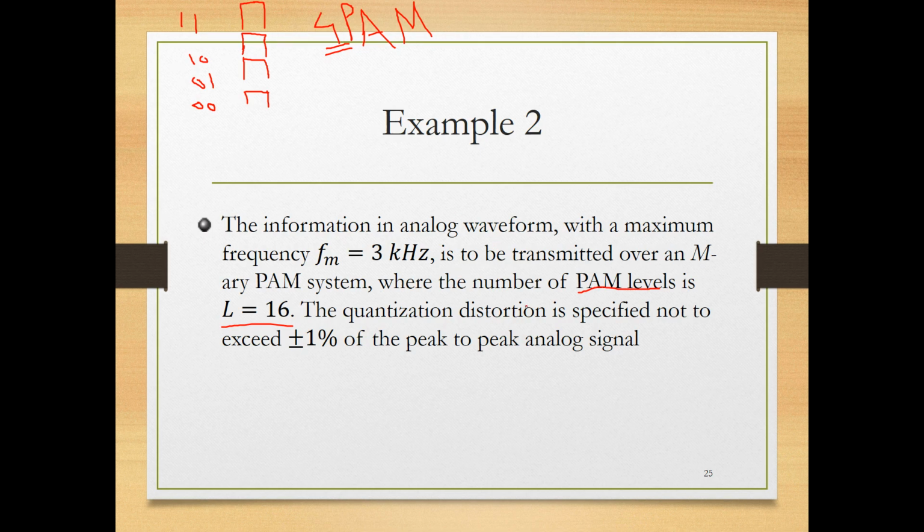This is what? The quantization distortion. What's the quantization distortion? Error. The error. And what would be the maximum error you can make in quantization? Delta over 2. Yes, delta over 2 is the maximum possible error you can make, because your quantization error is bounded between minus delta over 2 and delta over 2. It can take any value between these. The maximum error occurs when the error is exactly at minus delta over 2 or delta over 2.